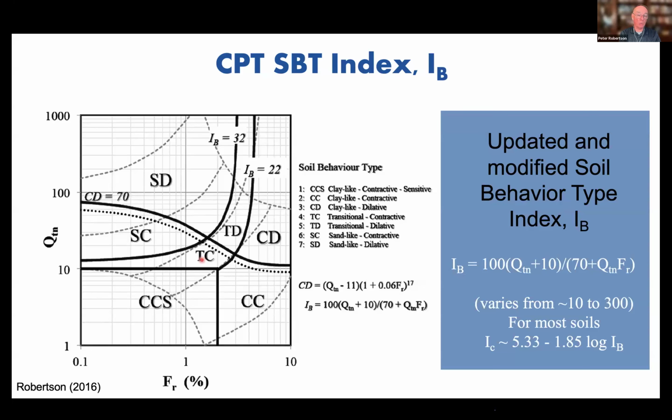And the reason we want to know whether or not a soil is going to be dilative or contractive at large strains is that if you have a soil such as a clay, and it's going to be contractive at large strains, like a typical soft, normally to lightly over-consolidated clay, if you shear it, it will have a tendency to contract.